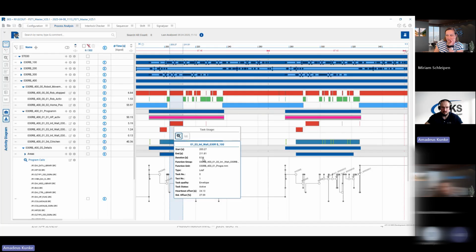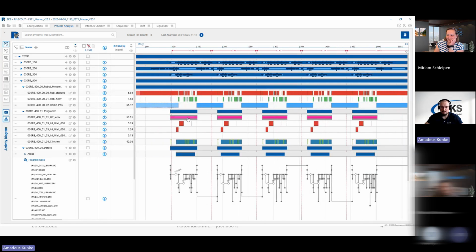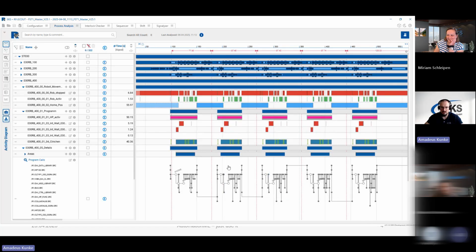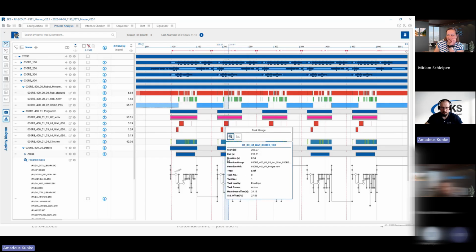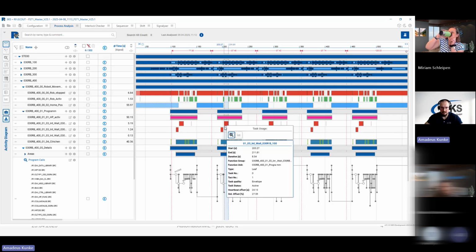That's 8.454 seconds, excuse me. And these seconds he has to wait always. You see that's appearing over each individual cycle. So you see different cycles of the robot here, and always there we have this waiting time. And therefore we could say, okay, that's something we can optimize. So we can say this movement in between, which is here quite short, and most of the time they are programmed like take the most speed as you have and move there. We can make this really small. So we take a little bit off the total energy consumption, which is always or most of the time very high because they're going always max speed. So we can optimize this here.